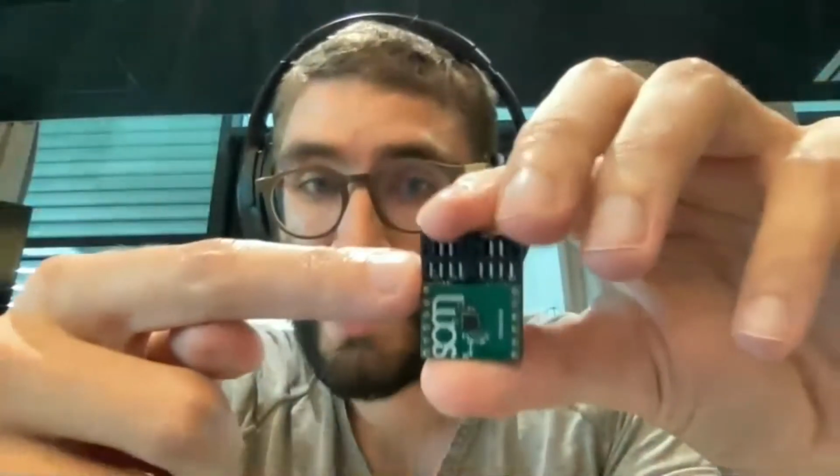So on this board with the motion sensor, I put one service, which is a driver service. We make a difference between a driver and an application service, because it's really important to separate services linked to the hardware from software that defines the behavior of your machine. It's important because if you change the hardware, you don't have to change anything in the behavior. You only have to change something on the hardware side, on the driver side. So it's really important to separate drivers and behaviors, or application services.